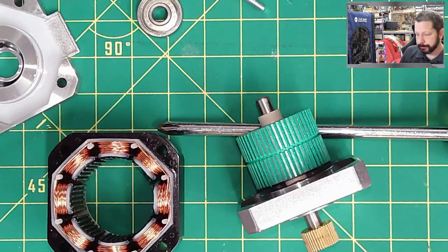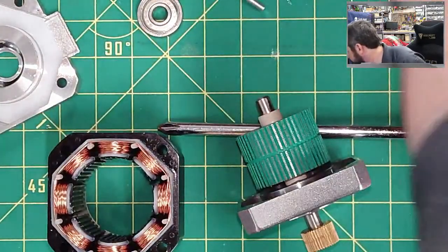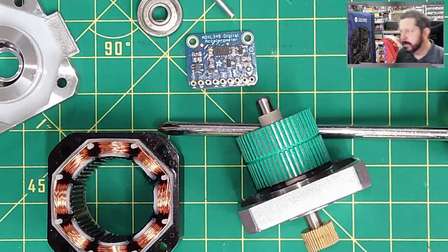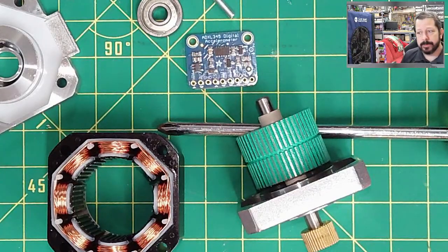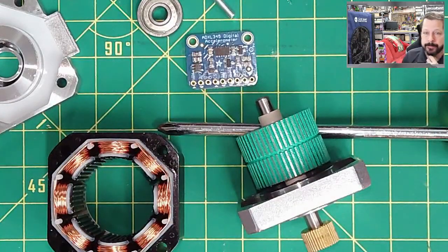Input shaping: you actually take, let's see, I had one around here. Here we go. You actually take an accelerometer like this one and mount it to the parts that are moving on your printer. Record the acceleration of the bed in something like the Ender 3. You record the bed moving back and forth. You record the print head moving left and right with this strapped to the bed and then strapped to the print head.